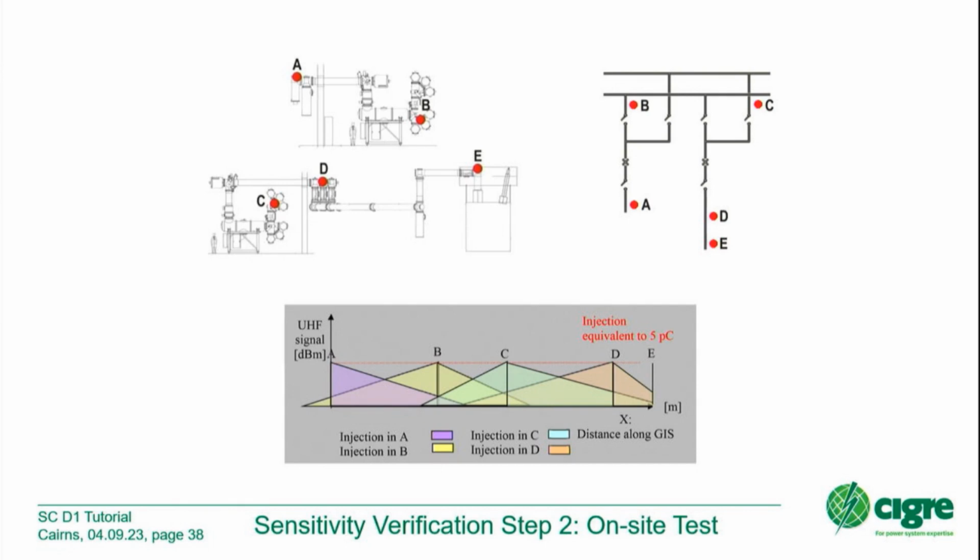This is a very simplified example. We came up with an ultra-high frequency attenuation profile. And it cost us hours of discussion because in truth, this is not a straight line. This is like a zigzag line, depending on the compartments in between. If you have a passive GIS module, or you have a module with a current transformer that changes, so you have this zigzag line, and this here should reflect to that. That's all. Okay, it's a very coarse simplification. Yes, and maybe if you want to look for a technical explanation, maybe this is a really big tube, so an increase of diameter from 500 to 1 meter 20. But you understand that, yeah?